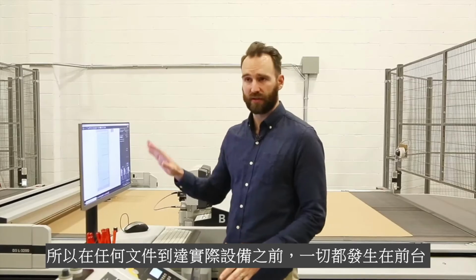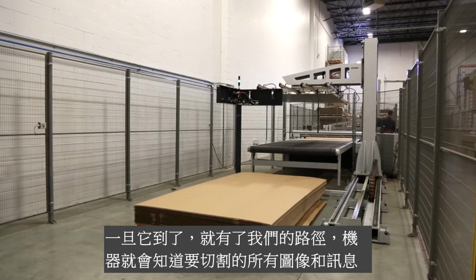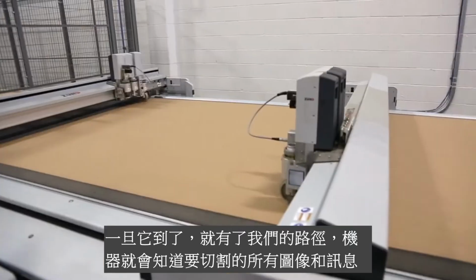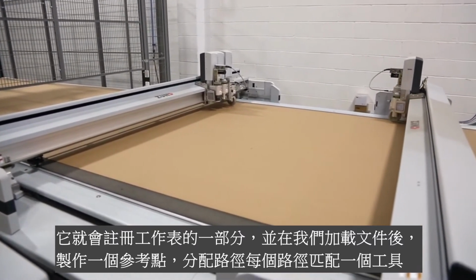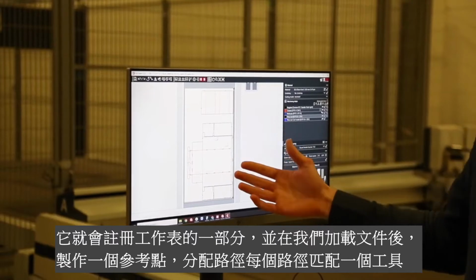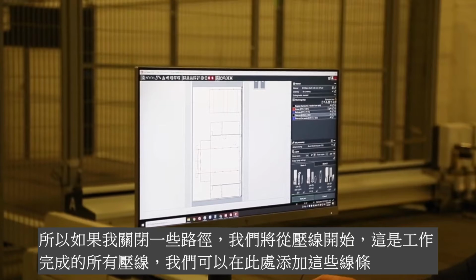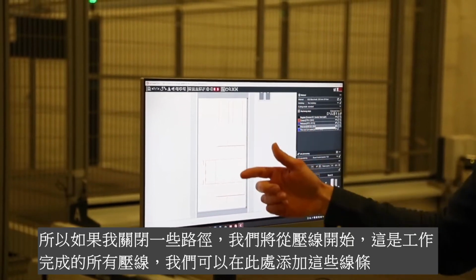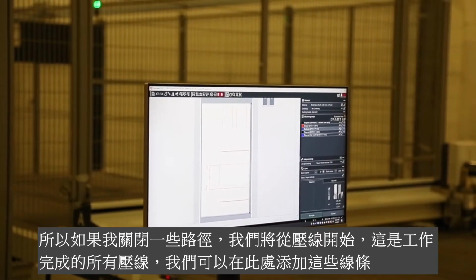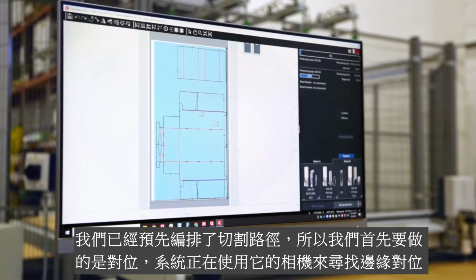So before any files get to the actual equipment, everything happens in the front office. Once it's here, we've got our layouts, we've got our die lines, all the images and information that the machine knows to cut. Once it's there, it's going to register parts of the sheet and make a reference point. Essentially, once we've got the file loaded up, it's separated into paths. Each path matches a tool. So if I turn off some of the paths, and we'll start with creasing, this is all of the creasing that's done for the job. From there, we can add the perfing, which are these lines right here, and our cut path.